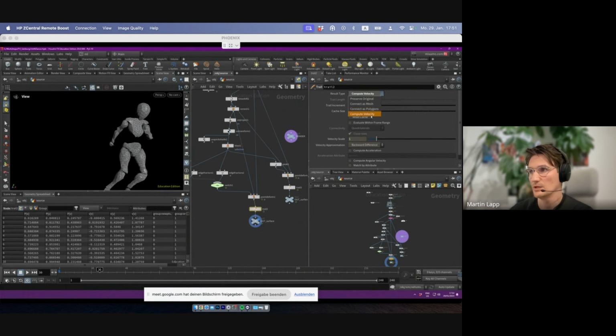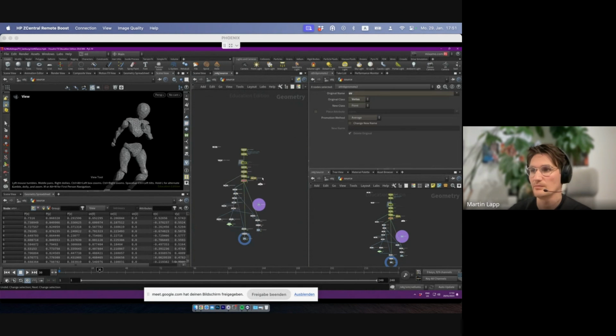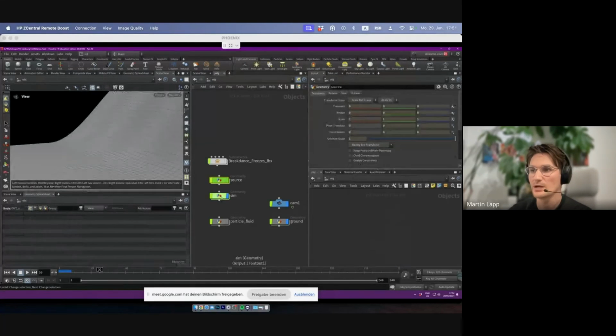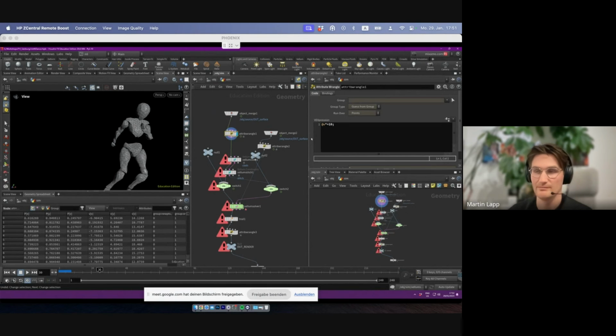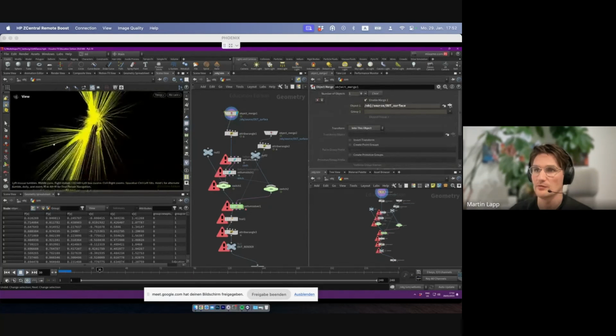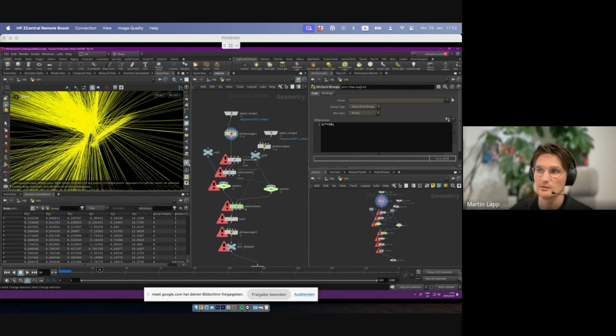Before, in the other setup, I said preserve original, so it created this kind of thing. Anyways, you can see this is all the same as the fluid guy, then this changed, and then this is the same again. Let's go to the sim part again. We're importing what we just created. Now this attribute triangle actually says multiply my velocities by 10. So my incoming velocities from the trail are just multiplied by 10, so we get extreme velocities in the beginning.